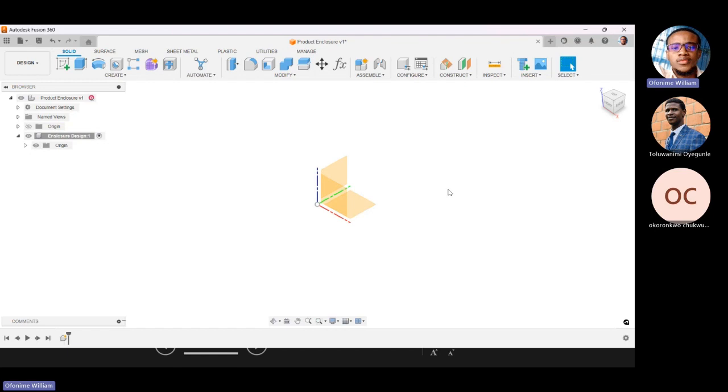You understand? So when you look at both of them, you find out that PETG on the other end is more durable, has some flexibility. So it means it has the ability to readjust itself, if it's a little bit deformed. But on the other hand, your PLA plastic, after exceeding its yield point, would do what? Just break. You understand?